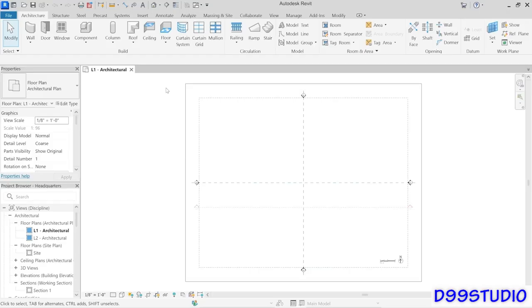And should you crash, should the power go out, should something happen, you will be very unhappy because you will lose a lot of work. So it's very important that you understand that. Sometimes folks are surprised to hear that and they just assume that Revit would have an autosave. It does not. Okay. Well, what it has instead is a save reminder.